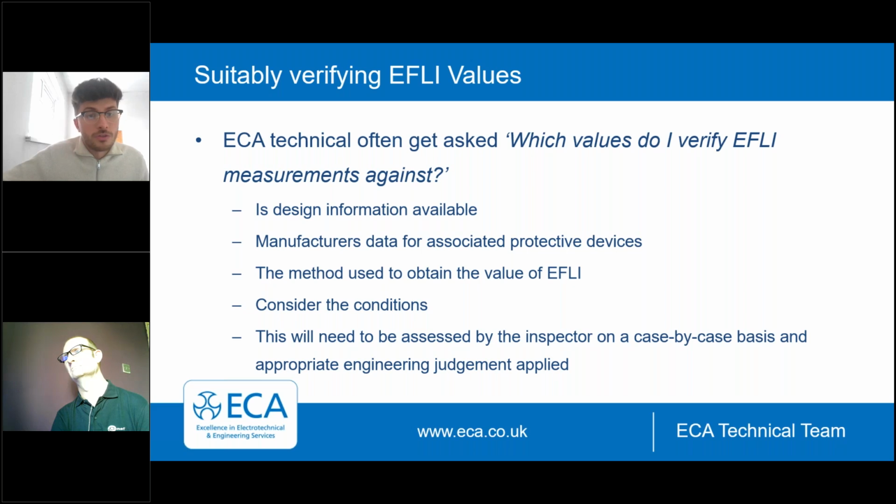If you do verify your readings against manufacturer's data, you should then attach that information with your handover pack, with your electrical installation certificate, or whatever document you're producing, and then detail, let's say, on the electrical installation certificate that the values were obtained via manufacturer's data. Okay, now the method used to obtain the value of earth fault loop impedance.